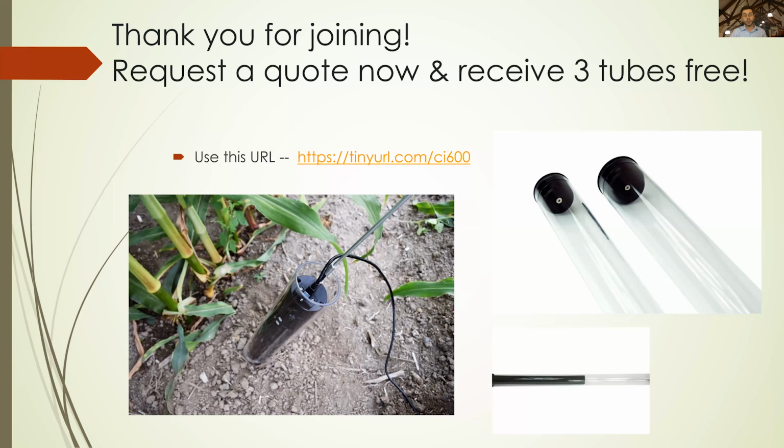So the next question we have is, with a 45 or 60 degree angle, what is the soil depth being monitored? So we do hand out 1 meter tubes. However, you can use even longer tubes than that. So you can actually just do a soil depth of, I would say, 2 meters fairly comfortably, given enough sliding rods. After that, it gets kind of difficult to handle just as a person. You need more like machinery in place to do that. But you are able to do scans at each one of those depths. So that way, if you want to get a massive picture of what you're looking at, you can stitch all those scans together.